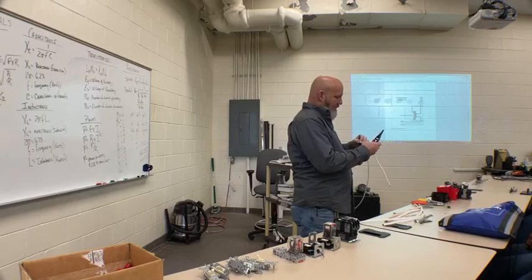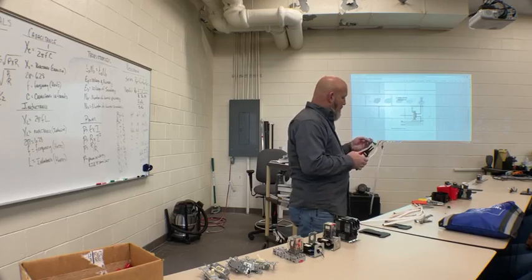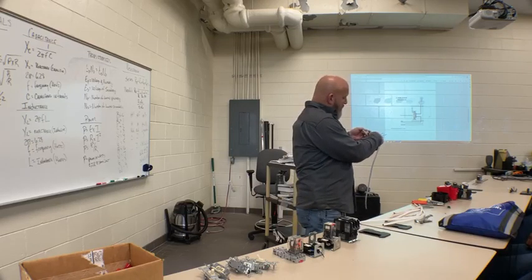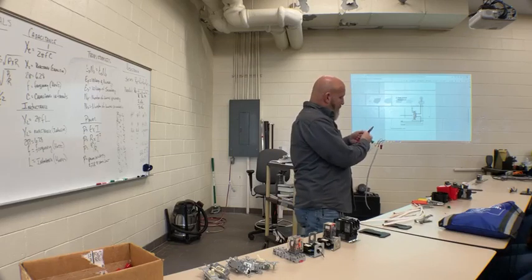You don't have to try to hook two wires around it. All grounds must be connected together. So this connects this. This right here would go to your light fixture, and if you had a ground on it, you would ground it, and it's connected to this ground.